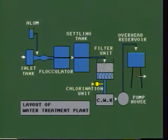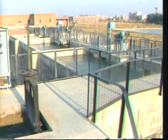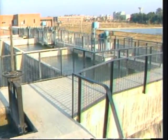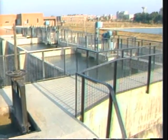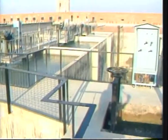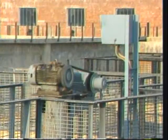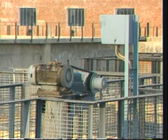The next unit of the treatment plant is the flocculator. Here two different flocculator units are used, one at the right and the other at the left. In the flocculator, the motor rotates the impeller with blades which agitate the water-alum mix so that flocks can be formed.